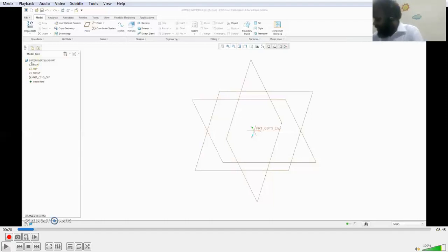I just want to probe a little. Say this is a flask of varying diameter, a shape which is curving down and leads to the bottle cap. So what is the feature that we are going to use to build this kind of model? Say it is cylindrical and conical at the top. Can I use extrude? No. It's better we use revolve as an option. Cut this, use this feature and revolve it with a center line. So this is easy. We know that.